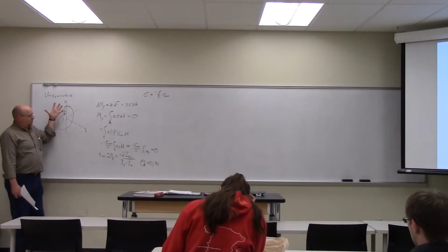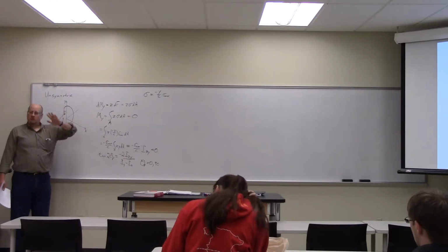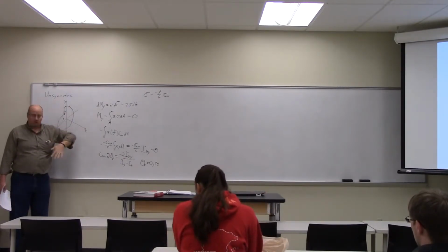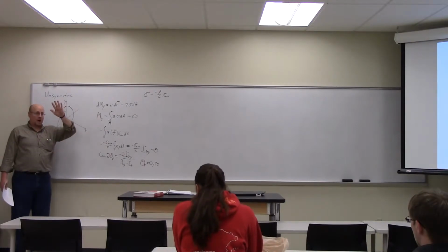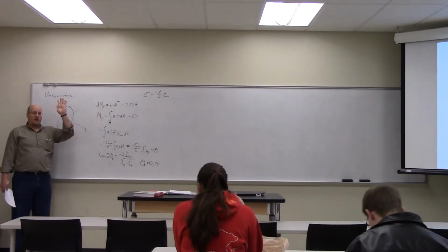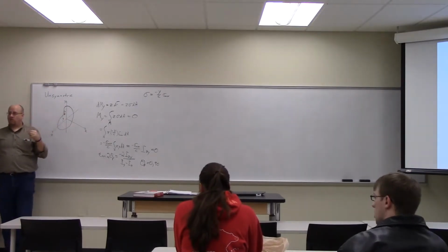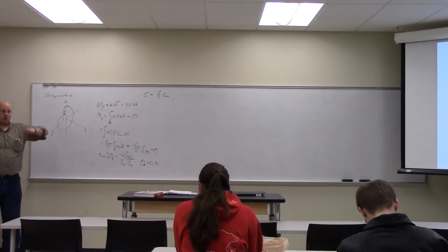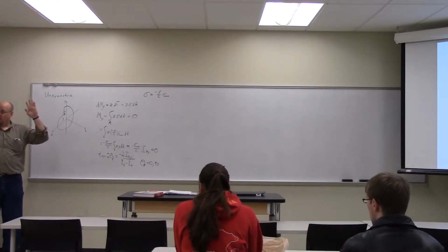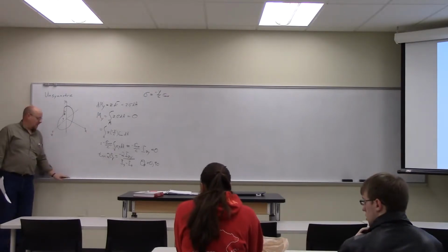So if I have an unsymmetric beam and I bend it purely, meaning apply a moment in the y and it bends purely in the y, that means I must already be aligned with one of the principal axes, either the major or minor moment of inertia, so max or min.